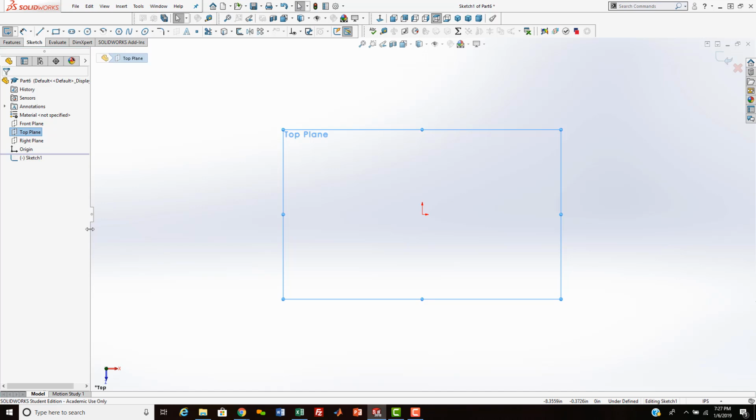Now the first thing it says to do is to grab the circle icon. So up here, this toolbar now became active because we have the sketch open. So this one here is a drop down for the sketch. This is for your dimensioning, your smart dimensioning, horizontal, vertical, ordinate dimensions, horizontal, ordinate, vertical, and path length dimensions. Okay, I always use a smart one unless I'm doing ordinates in my drawings.